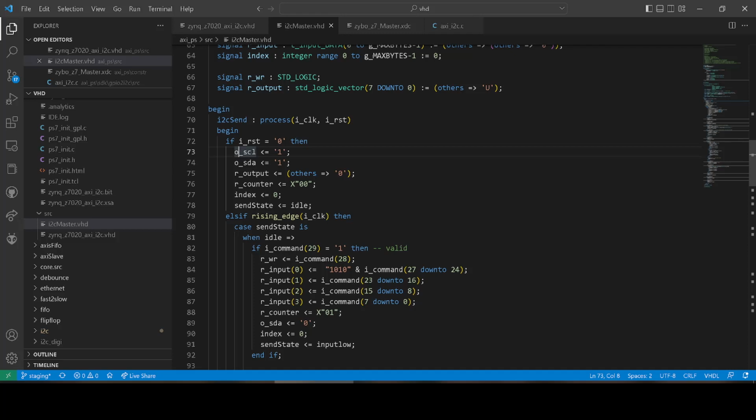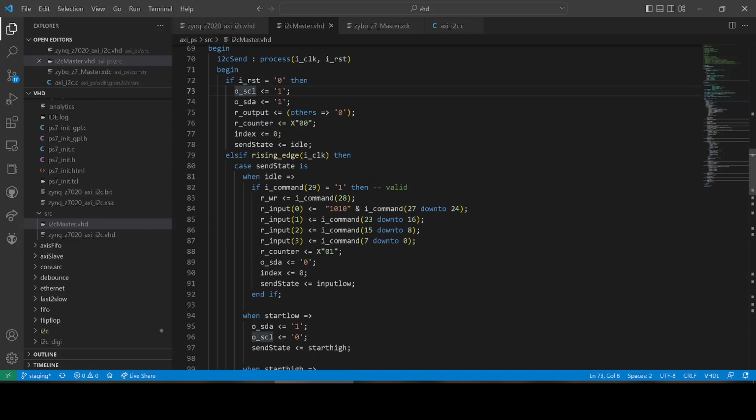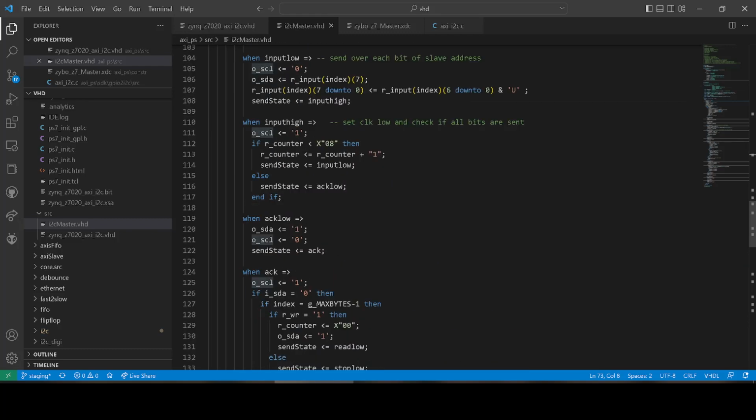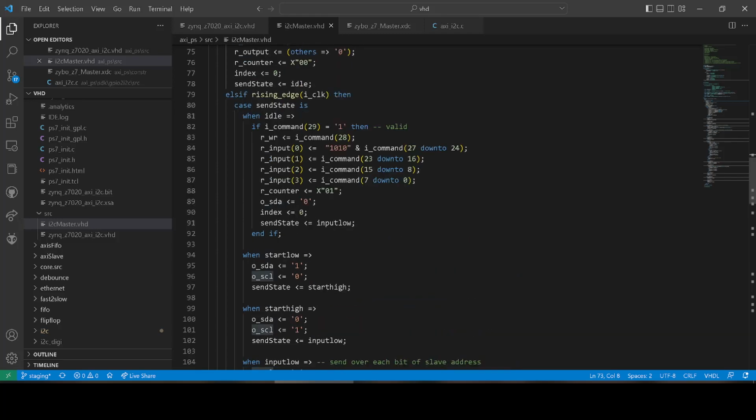And then here we're saying bit 28 is my read/write. And then here's the A that would normally be there, but it's there every time. So it's basically A plus my command. And then here's my high bits, here's my low bits, and then here's my actual either write data or the read command. And then, of course, throughout here you've got the logic, and I just realized you can't see my pointer again. I'm sorry. You should be able to see it there again, highlighting.